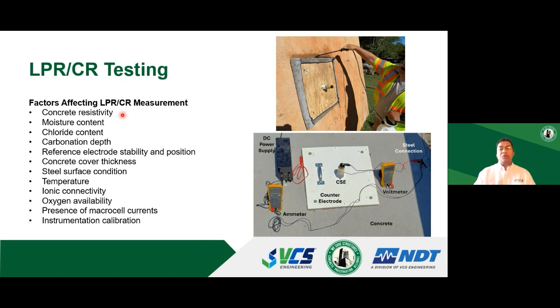There are third-party manufacturers who make corrosion rate devices. Just that caution must be exercised while using them. The data derived from the test should be applied properly because, as I said, this is an instantaneous corrosion rate measurement. It cannot give you an average value. It's the value of the corrosion rate at that point in that moment in time. It can change after 5 minutes, 10 minutes. It's a highly variable test.